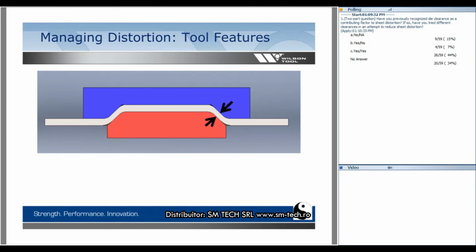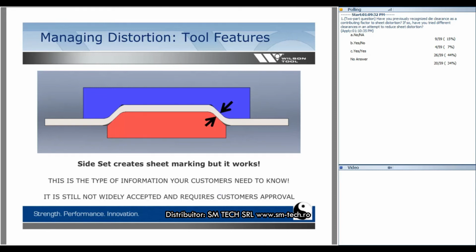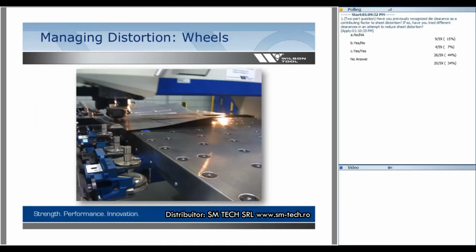Another feature would be something as simple as pinching the sidewall of that form, right? When we put side set, it's going to change the appearance of the material. I describe it as it's going to be shiny on the sides. It's pretty effective. It's often the solution. The first thing we do when a form distorted to the point where it tore, in essence, we go back, let's go smash it back together. So it's very effective. So if people can accept a shiny wall, looks pretty good.